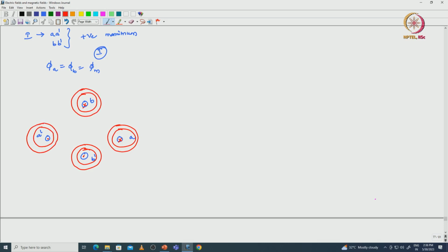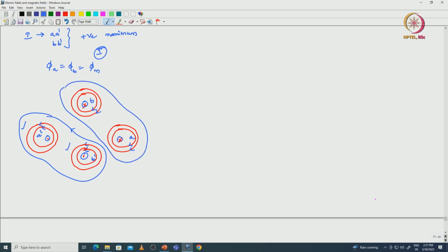So, in order to find the direction, apply the thumb rule. For dot it is anti-clockwise direction in this manner, for cross it is clockwise. So, these two flux loops, this one and this one, are additive, and we can find the resultant flux loop will be in this manner. With respect to the cross loops, these two flux loops are also additive, and the resultant flux here is phi r.